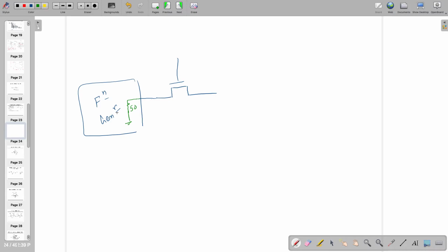That there is a 50 ohm impedance and there is a capacitor. So when you are switching this off, there is an availability of extra charge in the channel. Half will go this side, half will go this side, because there is an approximation that this side also we are seeing 50 ohm. If it is not equal, it will be something different, right? So this was one thing we learned, and this kind of thing is called charge injection.